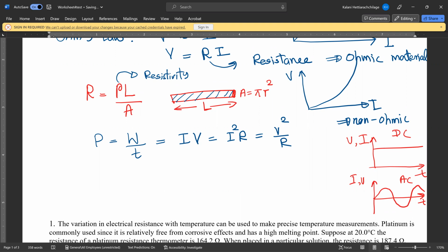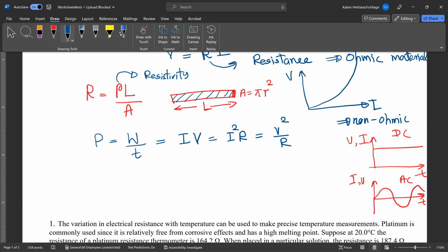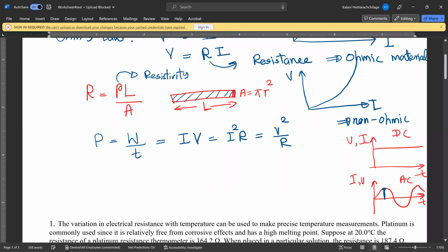So now how do you connect these two? That's the important thing. So now if I have, we'll say this is voltage, this will be my maximum voltage, or peak voltage, we call it, right? So now V_RMS is something sitting in here, the root mean squared value. That is kind of like an average, but it is not exactly the average. V_RMS is called the root mean square value. That will be your peak voltage divided by root 2, right?